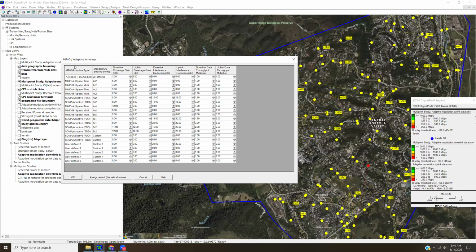Tirana uses a CPE or a subscriber device that has a big, massive MIMO antenna array on it, so it can leverage MIMO at both the base station end and the CPE end, which makes for a somewhat more expensive CPE, but also it means they have really high reliability and really potentially high data rates because they're leveraging multipath at the CPE end as well.